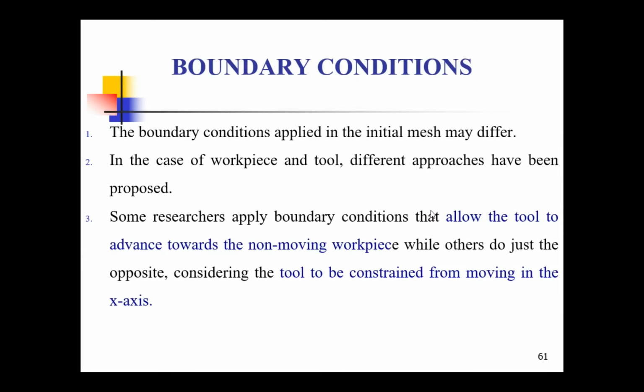Then boundary conditions. What are the boundary conditions? Which part is to move and which part is to be stationary, that we are going to decide. Some researchers use the movement of the cutting tool, and some researchers use the movement of the workpiece. If I apply a boundary condition to the workpiece, then the cutting tool has to move.